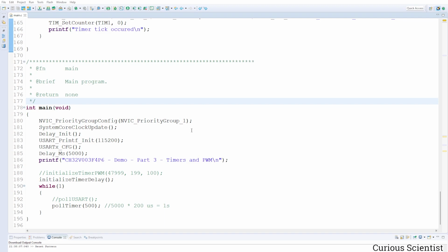And that is also very useful, because then you can do certain tasks when they need to be done, but you don't need to wait for them, let's say using a delay, but you can just configure the timer, and based on the elapsed time you can generate an action. For example, blinking an LED or running a function that reads out a sensor or something like that.